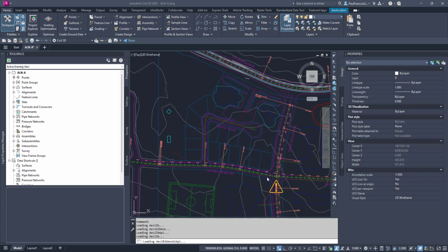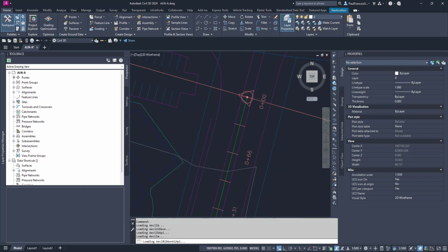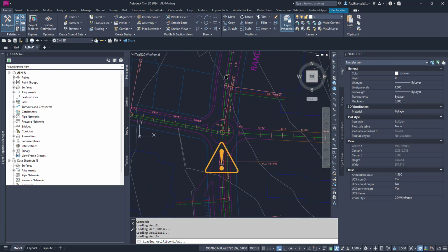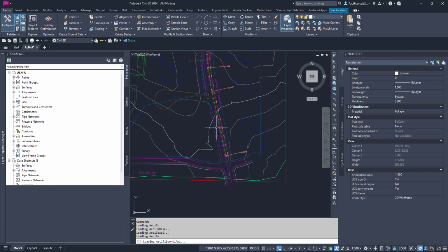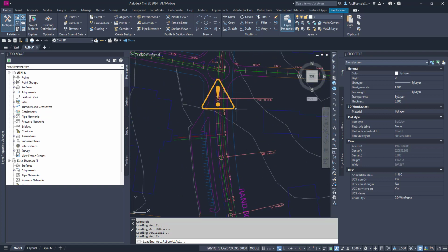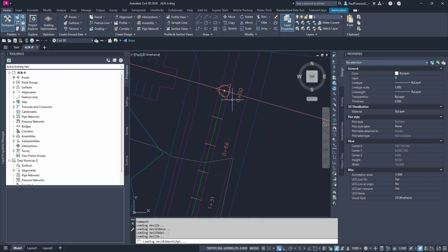I'd like to discuss with you the question in Civil 3D of how do you get to the alignment label sets. Alignments are horizontal paths that define, or are part of the definition of, a corridor that is built up. It works together with a profile to form a three-dimensional path along which assemblies are swept to create the corridor.